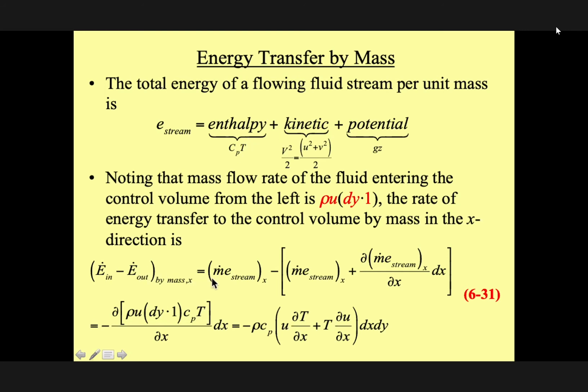Therefore, we write the energy that comes in and the energy that leaves. The mass enters the system in the x direction and leaves at a different position. We put the term in and this term disappears, and we look at this part, because this is minus this one. In minus out is the variation over the length delta x. There's a change of energy of the mass, and this is Cp delta T, the energy, and this is the mass of the fluid.